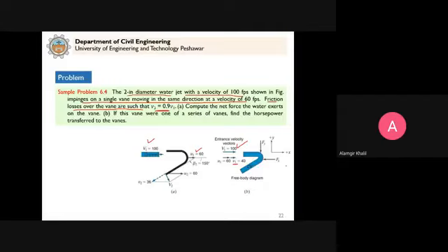So since the vane is moving, the fluid will enter with a relative velocity of 40 foot per second, because it moves over this vane, so there is friction. So it says that the exit velocity, relative velocity V2, this is the relative velocity. Clear? In this case, this velocity is 0.9 times the V1. So due to the friction there will be some loss of velocity, that is now 36 foot per second as the fluid moves over this vane.